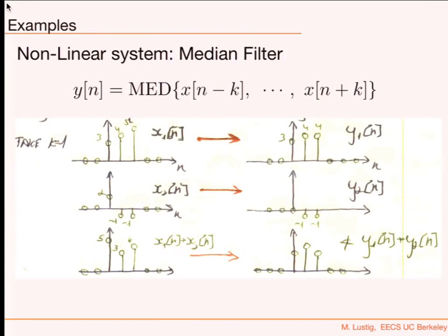I move it, I compute the average. I move it, I compute the average over a set of finite samples. A median filter is the same, but different. Median instead of average. Moved, median, over a set of samples. So it takes a median.